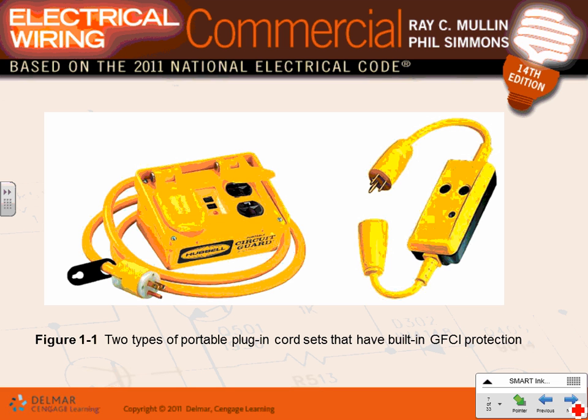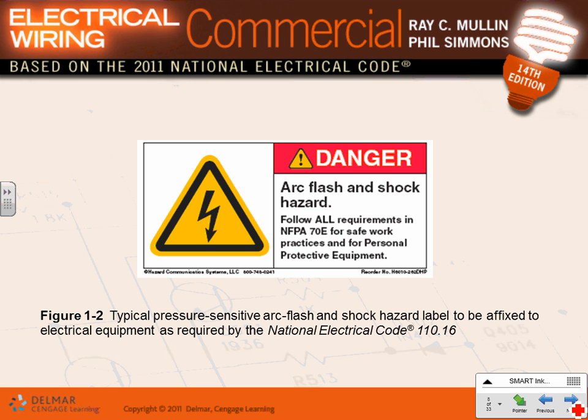Here's that stuff that you need to do. Portable GFCI protected plugs. All the panels, including this panel, I hope, have to have caution, OSHA, front and front panel. There is no arc flash label here. Oops, no, here. Arc flash label: appropriate PPE required. By code, by law, the NEC code book and OSHA require a label like this. So when the electrician, or you as an apprentice, is standing in front of a panel and the electrician opens it for you, you have to be warned that a big ball of fire could come out of the switchgear if you drop a screwdriver inside the switchgear.